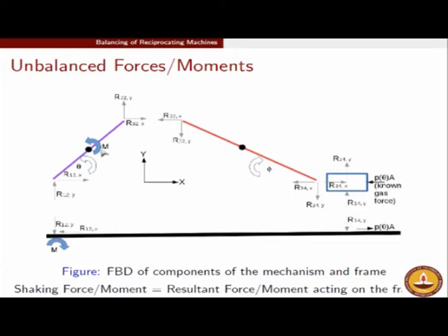By frame, I mean anything which is external to the moving parts. Anything external to the moving parts is equivalent to that load torque, and therefore a reaction to that moment is coming on your frame also. I hope that clarifies the question.